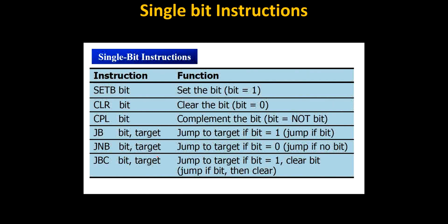For that we have some instructions. I can use the set bit instruction, SETB. Whichever bit you specify, that will be made 1. Clear bit, CLR, clears that particular bit. Next we have the complement bit, CPL. We should remember all these instructions: set bit, clear bit, complement.